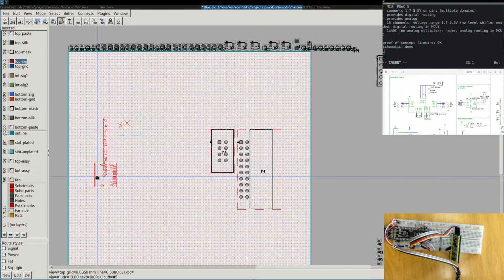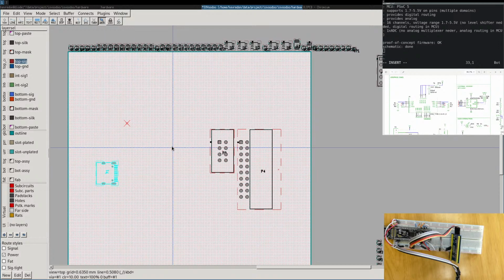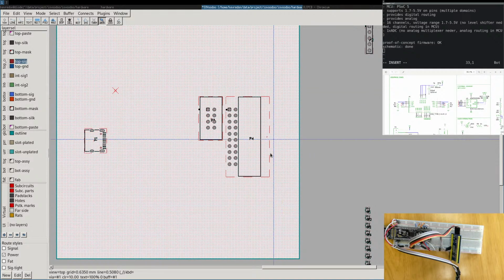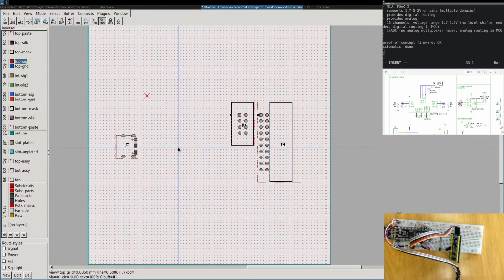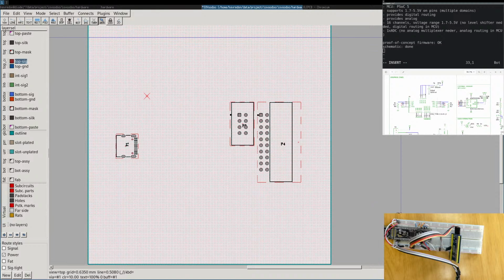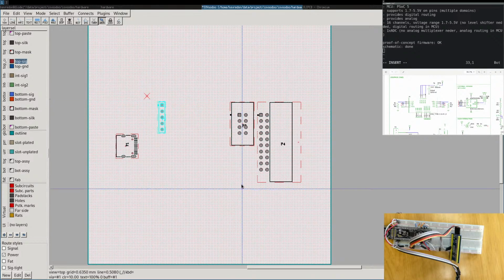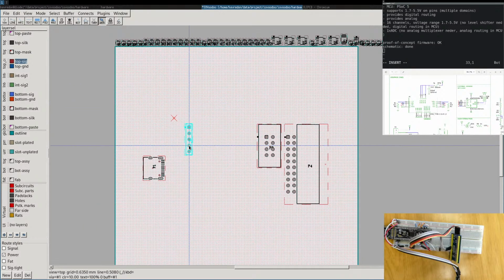So the USB connector will be this side. If possible, I can make it 5 centimeters by 10 centimeters. This way I can have 2 per 10 by 10 board. This is the programming. The programming board will be next to the microcontroller. Although I will put shrink tube on it, so we will not put it next to the microcontroller. We will put it next to this connector. The connector should be centered.